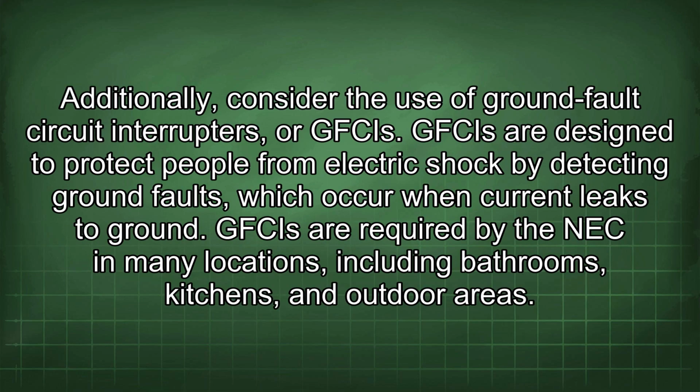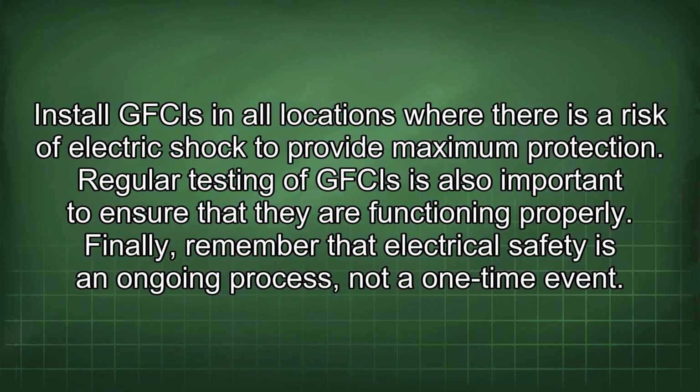safety. Additionally, consider the use of ground fault circuit interrupters, or GFCIs. GFCIs are designed to protect people from electric shock by detecting ground faults, which occur when current leaks to ground. GFCIs are required by the NEC in many locations, including bathrooms, kitchens, and outdoor areas. Install GFCIs in all locations where there is a risk of electric shock to provide maximum protection. Regular testing of GFCIs is also important to ensure that they are functioning properly.